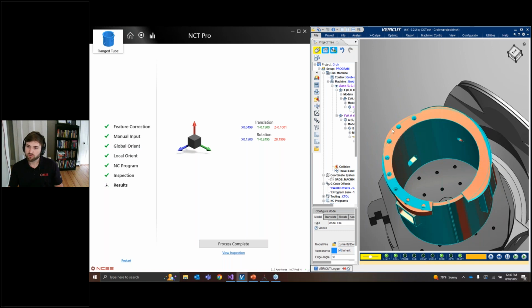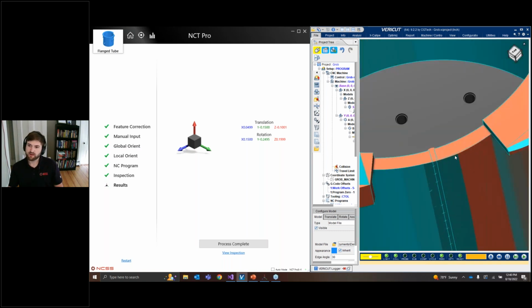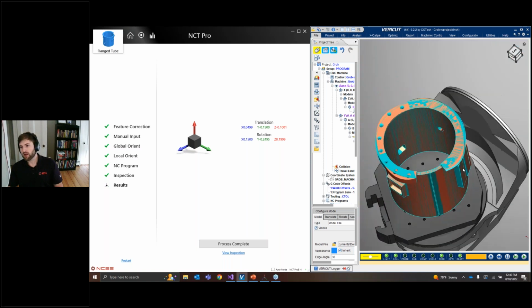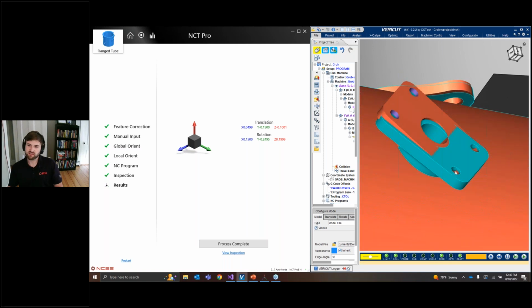And the same thing with holding along this edge with the countersinks. If I zoom in here, you can see there's about a 70 thousandths mismatch between these two edges where it was welded together. And we were able to blend that out perfectly. One thing I think is really cool is just how far off this is. We were able to adjust that cutter path to match the location, both perpendicularity and location of that bore, very easily, just with a couple of probe points.